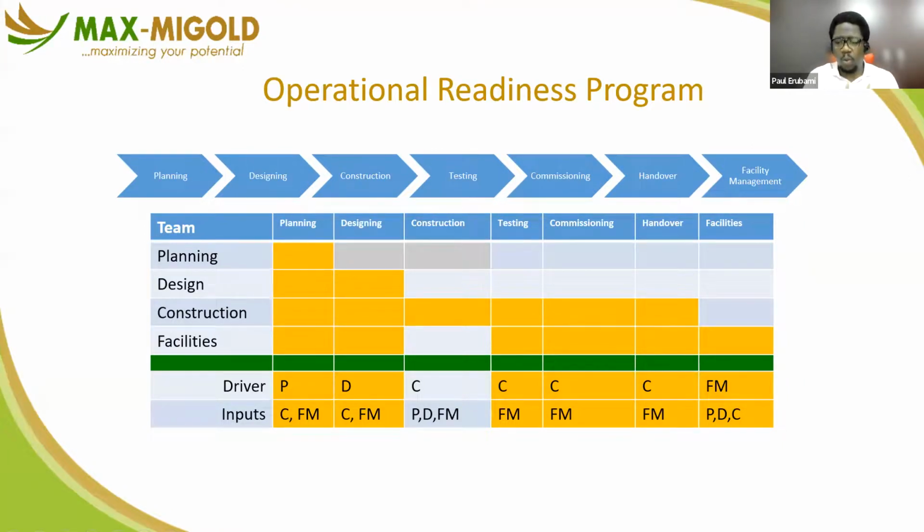The quality assurance and quality control. Quality assurance is a process of getting things done, documenting, and reviewing to get approvals to get things done, to ensure that the right things are done in the process to the endpoints. So if you are building a septic tank, for example, taking the right angles of the formwork using survey tools, right? And checking that the formwork is really square and in position before you cast or pour the concrete into it, or before you even bend the iron to do the reinforcement in it.